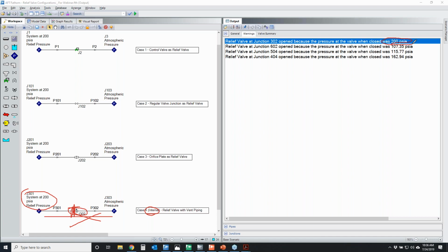That's what this message is telling me, and that's why it's telling me that my relief valve is popping open. My relief valve is clearly above the set point, which is 50 psia. That relief valve is popping open, and I am relieving to the additional piping right here. And as you can see, you now have solid lines, not dotted. That's because the relief valve has popped open.